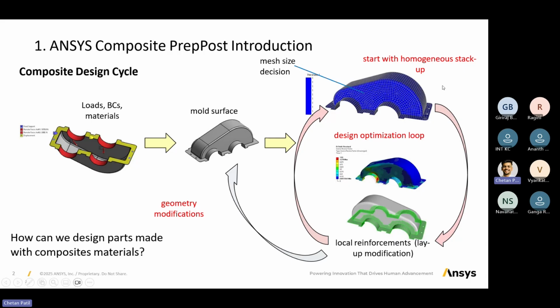So as you can see, if you have a particular model that you are going to use for the simulation, over here we just provide a mesh size to provide a random or an approximate kind of thickness, which is temporarily used at the initial. Then when you are going to use this particular model for the ACP module, you can define whatever material that you might be using, the fiber that you might be using, you can define its thickness to the geometry, and whatever thickness you did define at the initial will get changed with the composite thickness that you have applied.